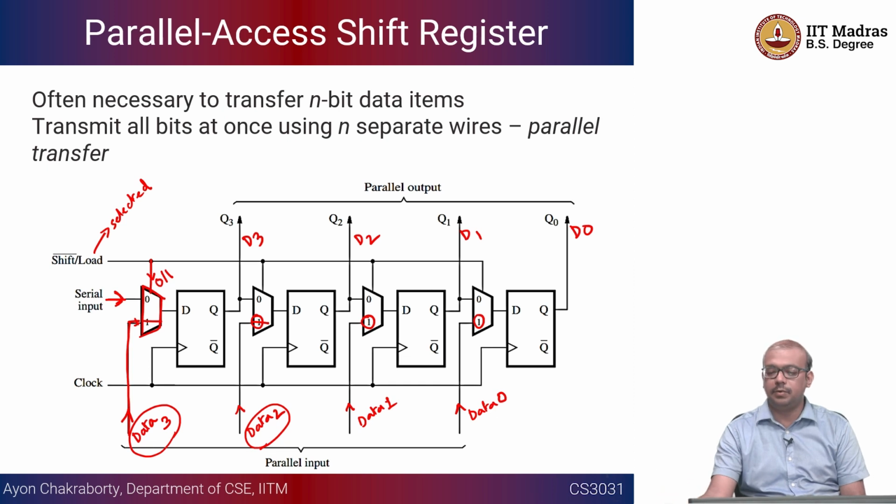Okay, so we have looked into the construct of a register using D flip flops. Then we looked into a memory block, which is nothing but a collection of registers, and at the same time you also have an address decoder to know which particular location is being queried. It could be either for writing or reading. And then you also have a multiplexer coming from individual flip flops, and you can give an output for a particular bit position.